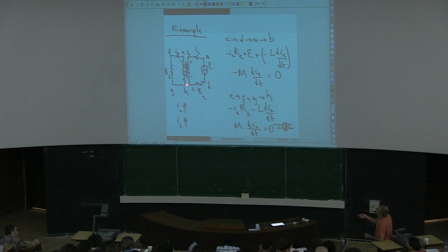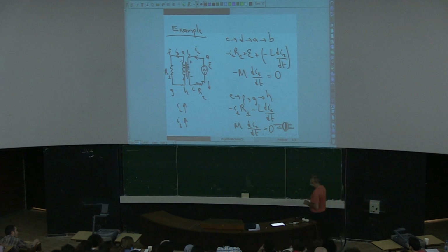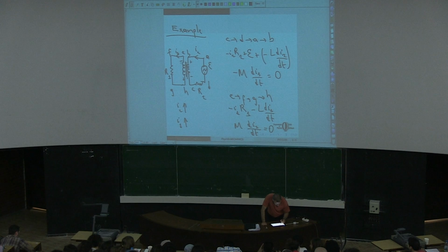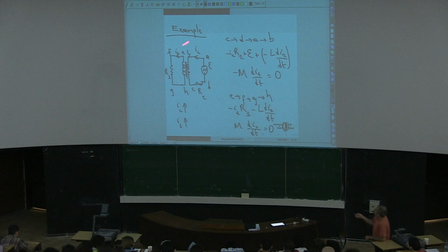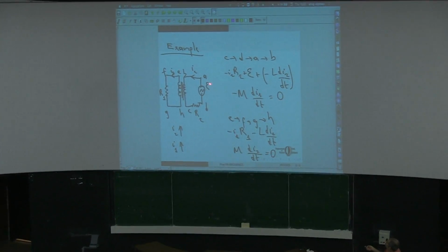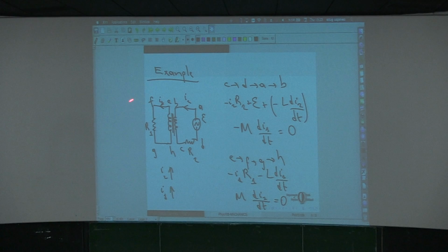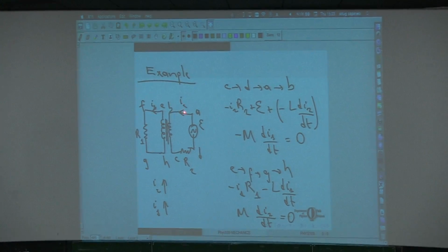Now, you see, these signs over here are due to the self-inductances, not the mutual inductance. So let me erase them. So let's see. What this term tells me is, we already said that if I1 is increasing, this device will create an I2 in the opposite direction, in this direction. If I1 is increasing in this direction, this will be running in the opposite direction.